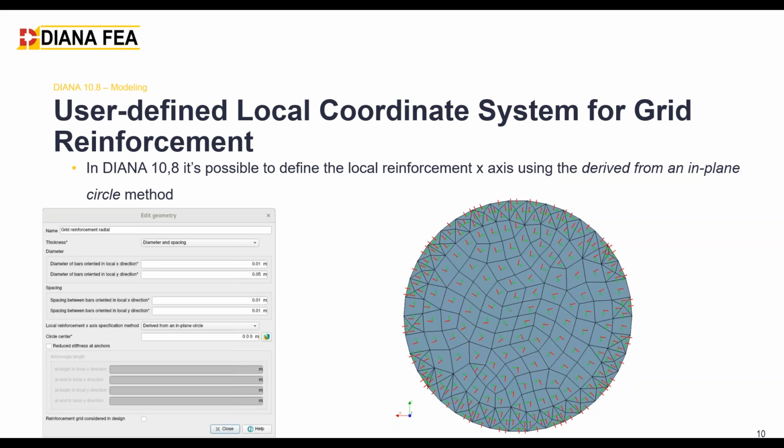It can typically occur in the construction of wind turbine foundations. So this is a nice feature, and you see that when you present the local element axis, these are following this in-plane circle definition, where the tangential direction is in the plane of the grid, the local z-axis is the normal, and x will be the radial.